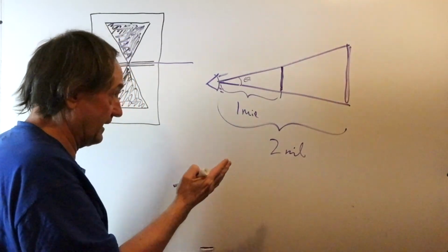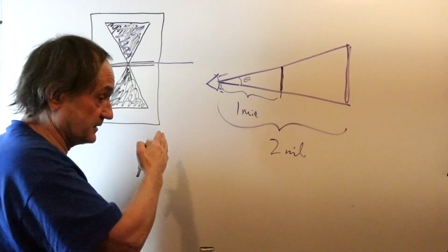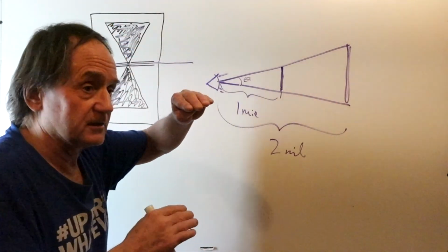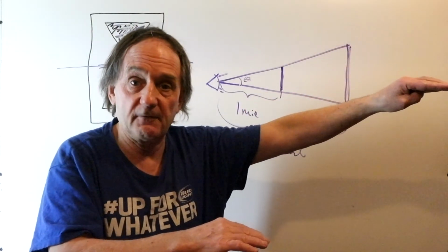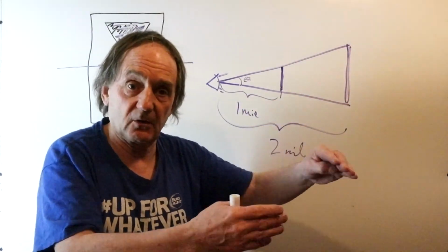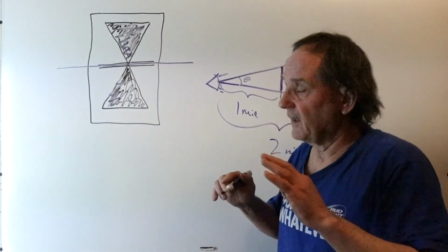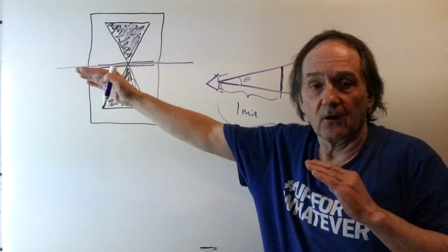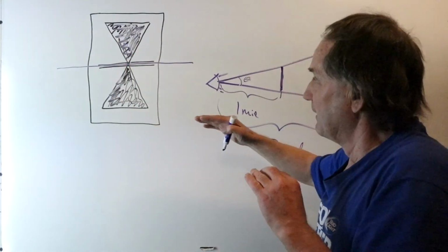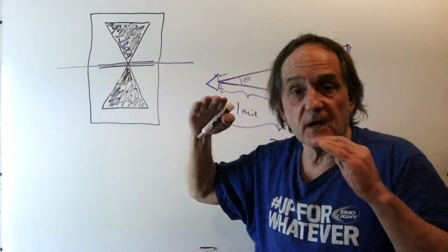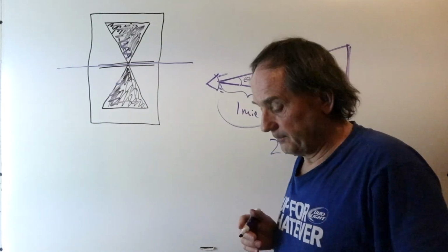So that's why I have different size targets. We put the larger targets further away from the observation point and the smaller targets in, and they are ratioed such that when they are placed along the measurement line they will all appear the same size in the spotting scope.